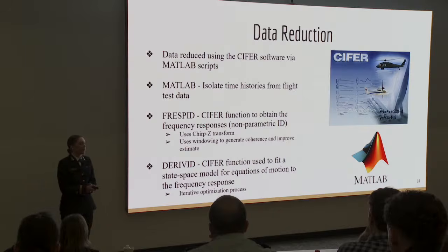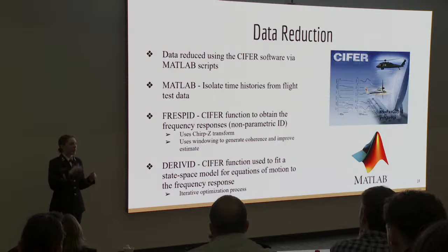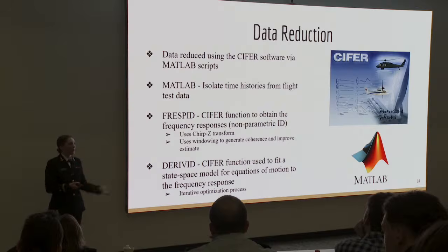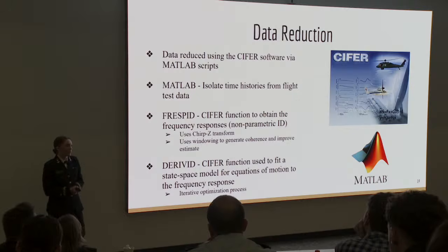The first step with our data reduction was, from the full flight logs of our flight test data, we had to isolate the time histories of just the frequency sweeps. ArduPilot records everything that happens in the flight, but we only cared about what happened when we were running our specific frequency sweep. So not the landing, not the takeoff, not the turning, just the frequency sweeps. So the first step was we had MATLAB code that would load in all the data and allow us to isolate that.